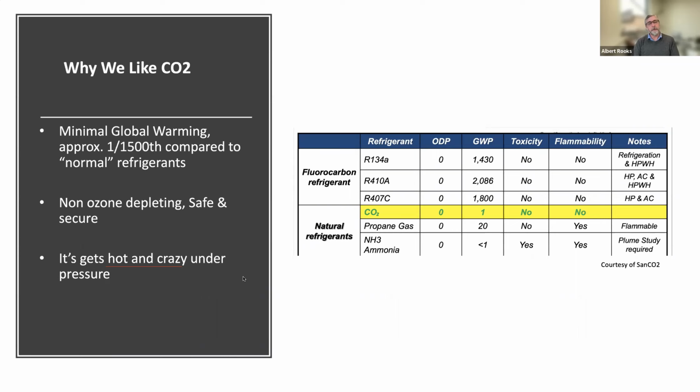It has a really low GWP, global warming potential of 1, and it will very easily lift 45-degree water to 150 up to 190 degrees in a single pass with very little energy input. It'll do that reliably in very cold ambience.